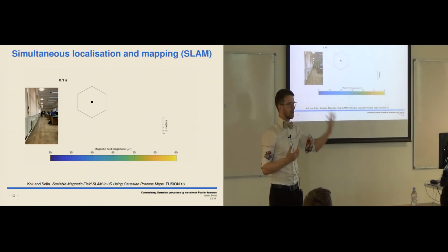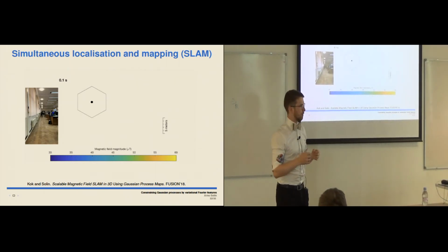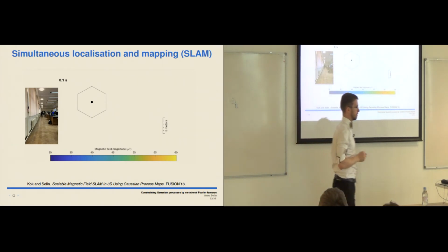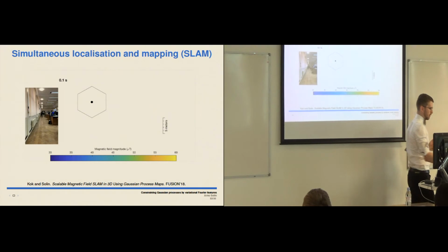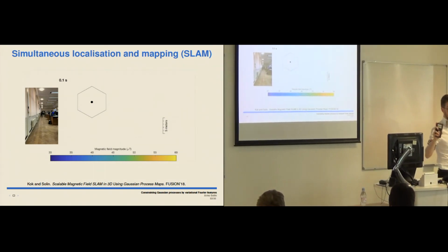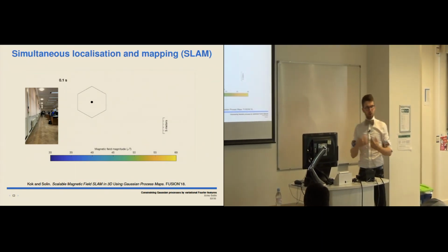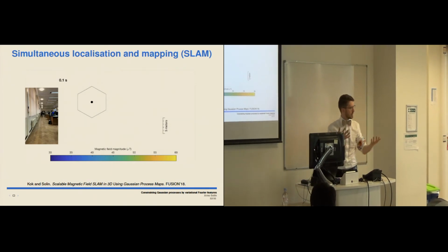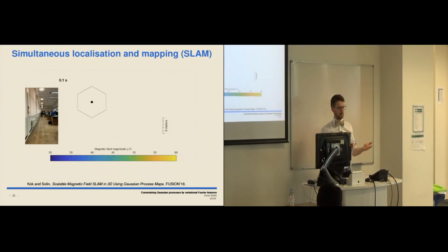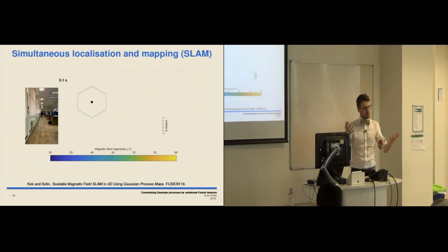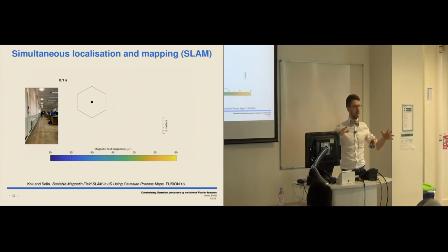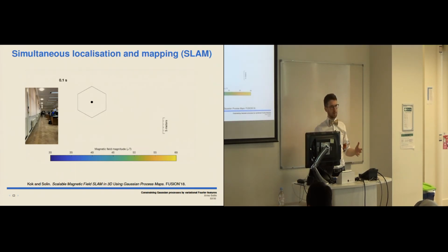SLAM is simultaneous localization and mapping, and a very particular kind of SLAM. Basically, the smartphones you have have a compass sensor, and that compass sensor is a magnetometer, which can observe, like what the compass does, the Earth's magnetic field directions. But you might not know that the local magnetic field, for example in this building, is disturbed by all the metal in the pipes and electrical cabling and so on. So actually there's a unique fingerprint, even in this space, for the magnetic field.